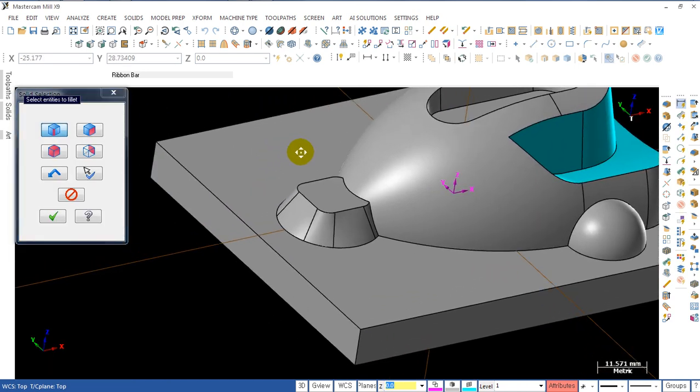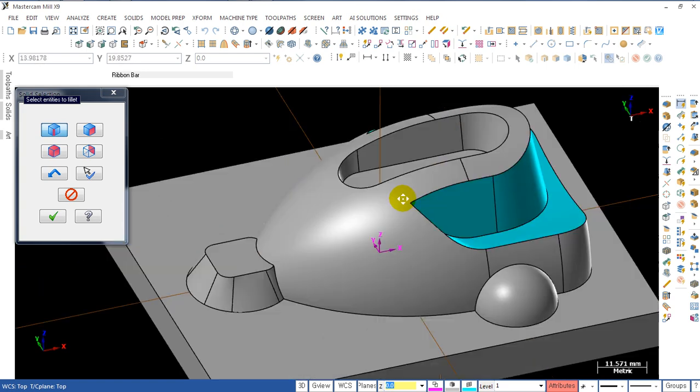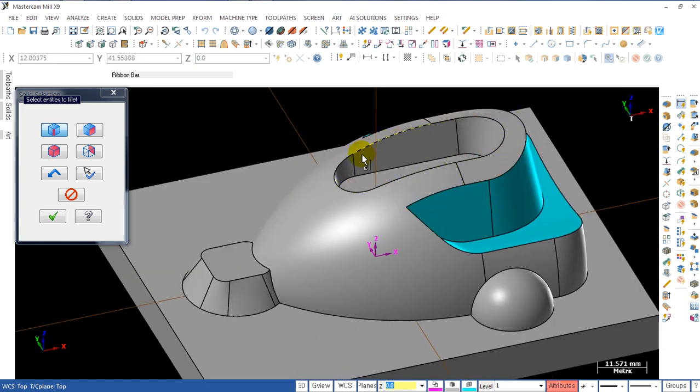And so all the fillet, the R value is 2 apart from this side. So this one is the radius one. So let's do it. And just select this part and this part, this part, and there's a tangent option. Automatically, some tangent part is the fillet.